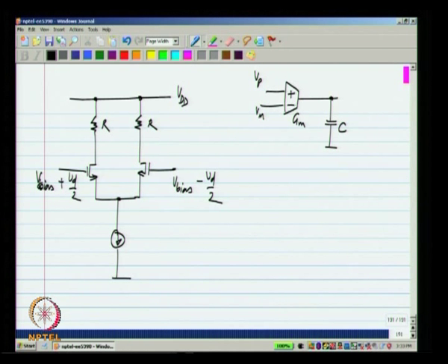Okay. Now, I know that whatever transconductance I make will have some resistance R naught, and I would like to maximize this. Okay. Now, if we compare this to the circuit that we do have, a circuit that takes the difference, and the incremental current in the transistors is related to the difference in the voltage. Okay. Now, the circuit that we have also has an output resistance, and also the way we have drawn the circuit, it is symmetrical. We want only one output. So, we will just take one of the outputs and ignore the other one, that is entirely possible.